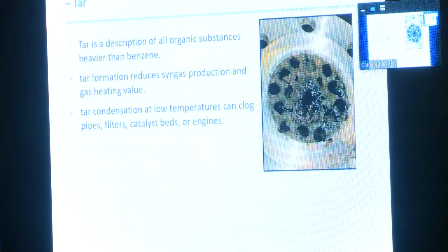So tar creates so many problems. As you can see here, first of all, if you remove it, you reduce the heating value of the gas. It can condense, cause clogging, and create many interruptions in the process. So we have to get rid of the tar.